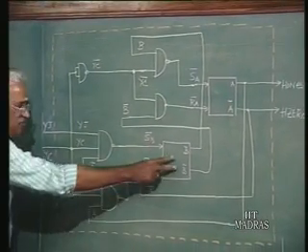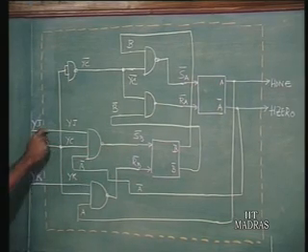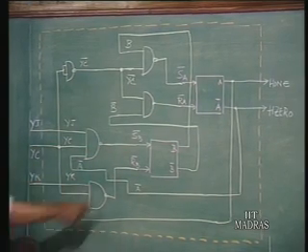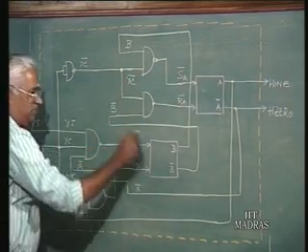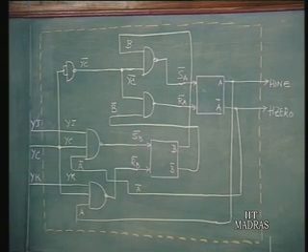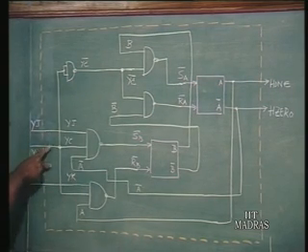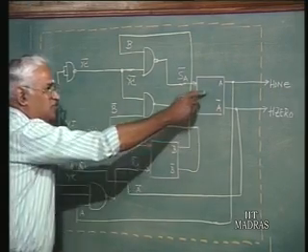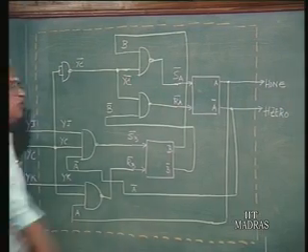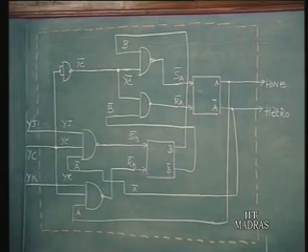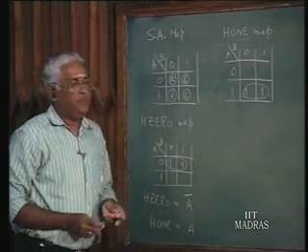You can just see B's input, if you take a look, it will be following the inputs, and A just follows B. So, A is the slave and B is the master. The master keeps an eye on the inputs, changes its states, and the slave follows the master. Good. It is a very simple output function, but nevertheless, even in the case of complex output functions, this is the way to proceed.